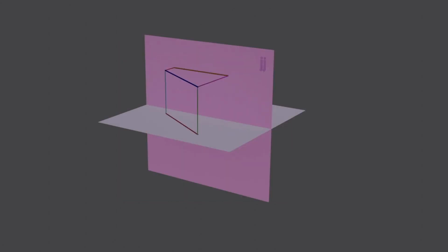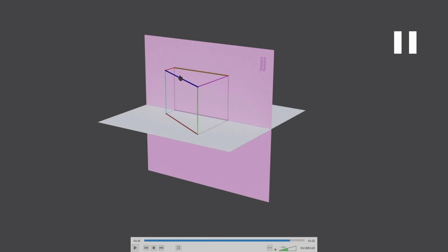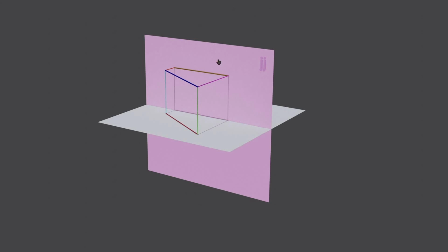So I'll bring that 3D view again, switch on the lights, make the markings. Right, now I've switched on the lights, I've got all the shadows. I've just made the markings there, that this is the front view, this is the top view. These two, the pink line and the orange line, are the distance from the vertical plane. In the previous portion we saw that when it was inclined to HP and parallel to VP, this pink line and the orange line were of the same length because that was parallel to VP. Right now it is parallel to HP, which means that this green line and the blue line are of equal length.